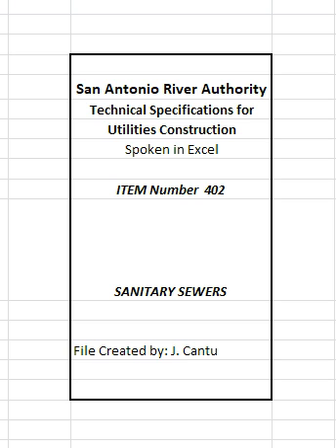All plans, materials, and specifications shall be in accordance with the Texas Administrative Code, TAC, rules to include 30 TAC 213, and design criteria for sewerage systems 30 TAC 217, or any revisions thereto as applicable. Contractor shall submit filed copy plans and profiles showing as-built work at end of project, CCTV DVD, and compaction density reports for main sewer line and all service laterals trenches. Warranty letters on materials and workmanship shall be for 24 months after file acceptance.